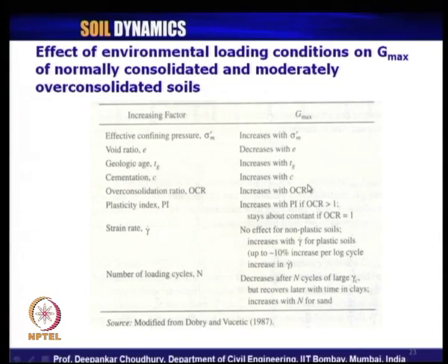Obviously, that will give a higher strength of the soil rather than a normally consolidated soil, which was not subjected to a higher magnitude of the load. Now, what happens if plasticity index increases? What is plasticity index? We know for fine grained soil, plasticity index is liquid limit minus plastic limit.